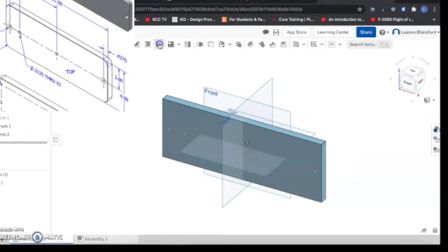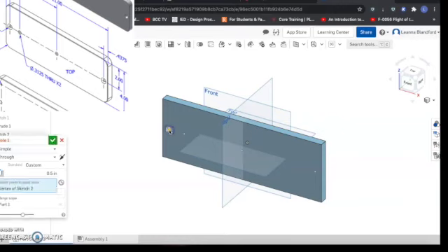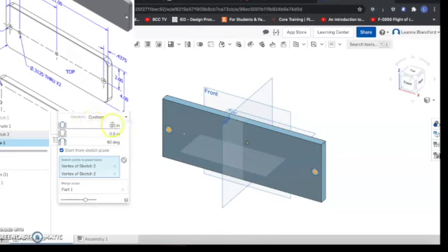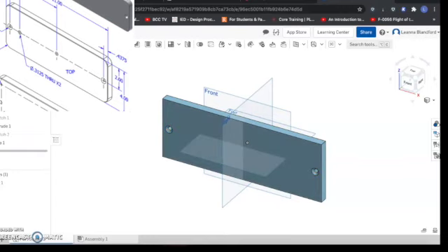So I am going to grab my hole tool and select both of those points because they have the same dimensions. And just like I did in my hole problem, I'm going to choose Countersink. Now I'm just going to fill in that information. The inside diameter of our hole is going to be 0.25. The diameter that goes across the top of the countersink is 0.5, so we can leave that. But this is 82 degrees, so I'm going to put 82. I'm going to hit enter, it'll make those adjustments, and then I'm going to hit the check mark.